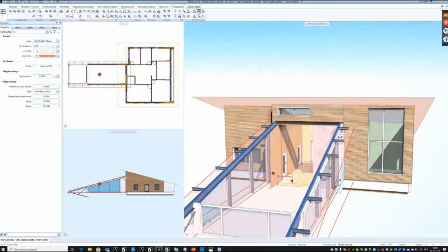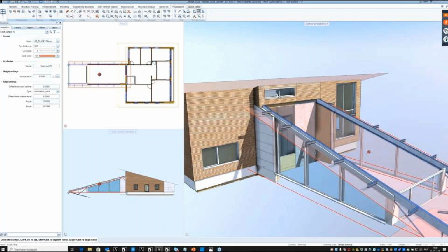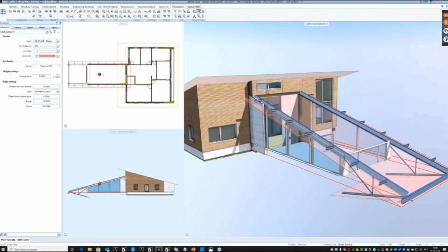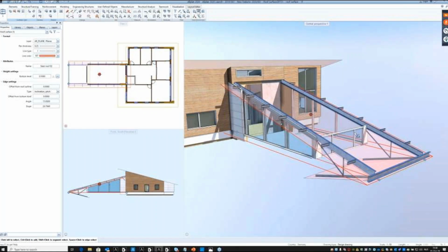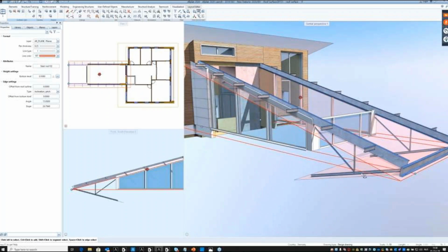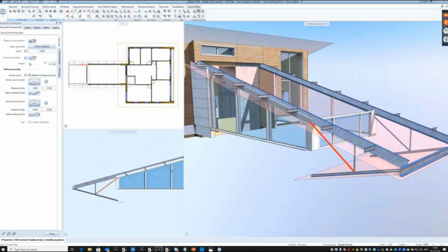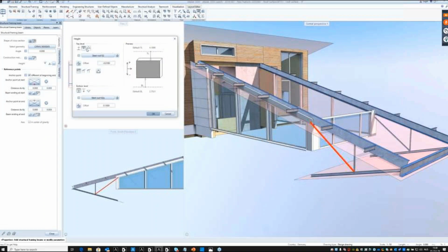So you see how easily we can adjust the slope of an already defined roof surface, but as you've seen in the previous movie, it's just about matching it in the plane, selecting a start height, and also in inverted slopes. You see here that there's an element that can be defined through two roofs.